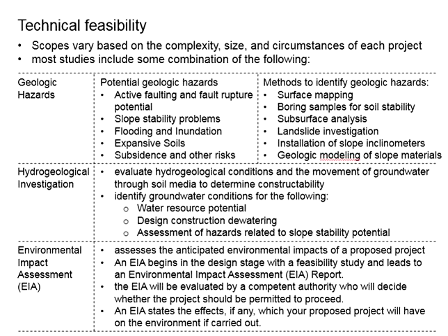There are also construction methods to physically withdraw the waters from the soil. This leads to rapid changes in terms of the groundwater table. As a consequence, significant settlements can occur.